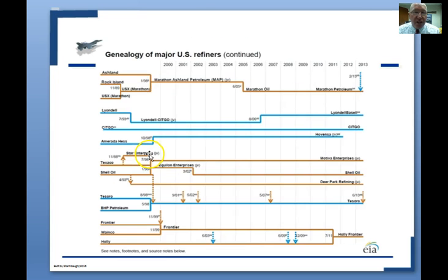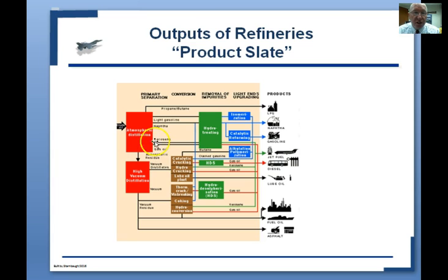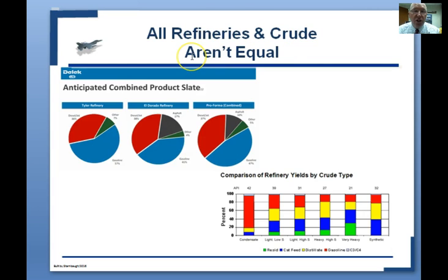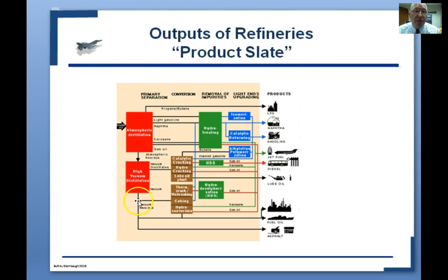You don't have to memorize those charts. I do want you to be somewhat familiar with this process, the refining process and the product slate. So remember that the first stop in the refining process are the distillation towers. And from that, you start to get the separation of the lighter materials. So this is where you would get off the naphtha, the LPG, and the gasoline, which you can get your first cut of just from the atmospheric distillation.